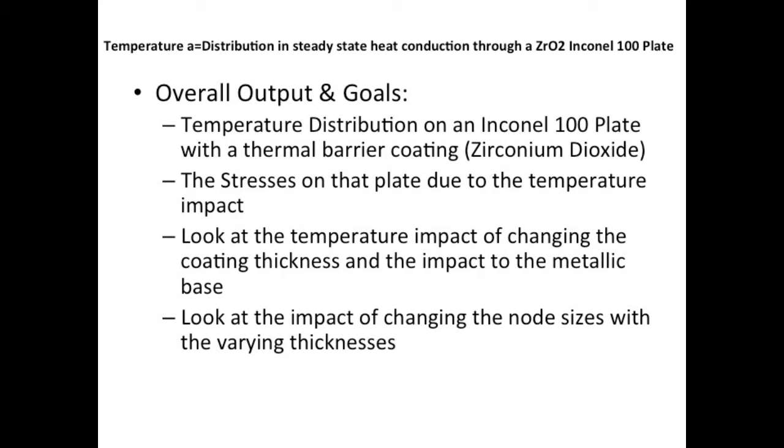For the final report out, the objectives and goals are as follows. I have looked at the impact of changing the coating thickness and what that does to the Inconel 100 plate. I will also be looking at changing the node sizes for both the zirconium dioxide and the Inconel 100, keeping them the same and increasing and decreasing that node size, as well as making it an uneven node size and seeing what the impact and the results of that are. The other thing that I'm going to do next for my final project will be to go into COMSOL and 2D and 3D model the results.